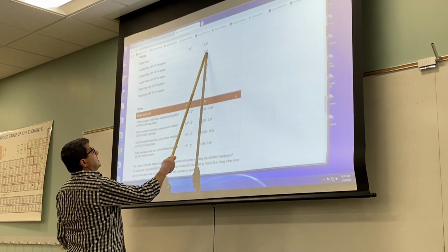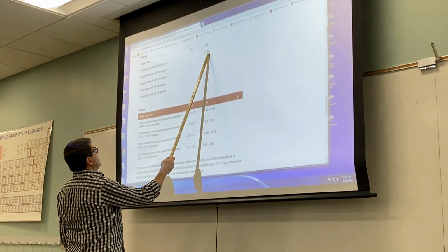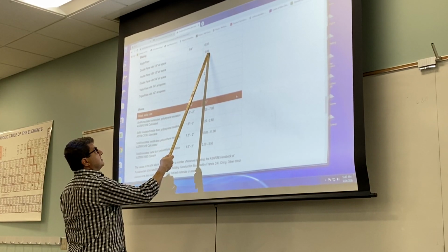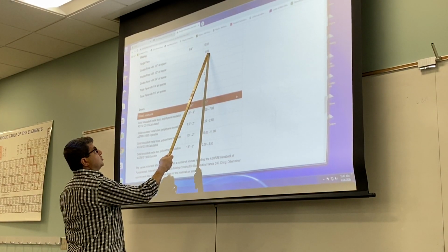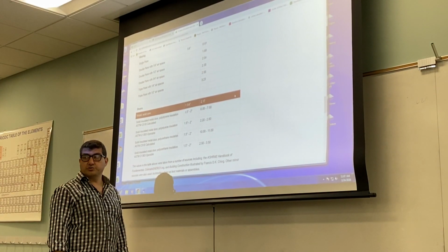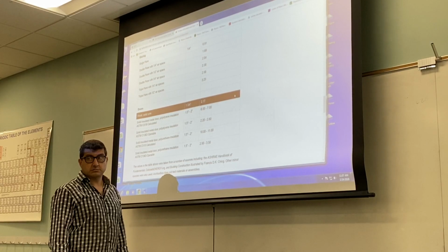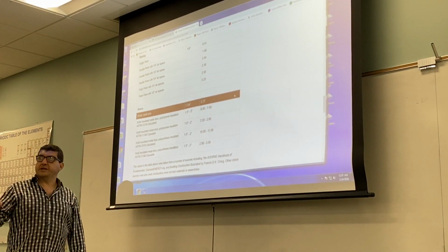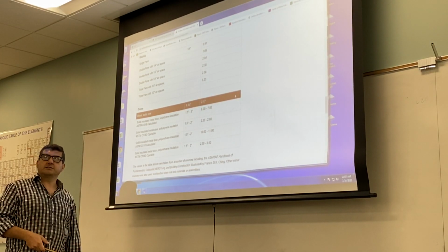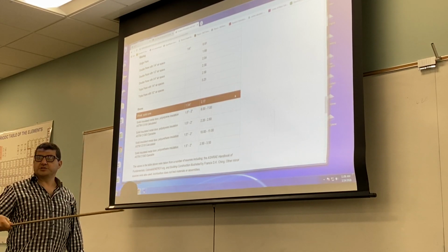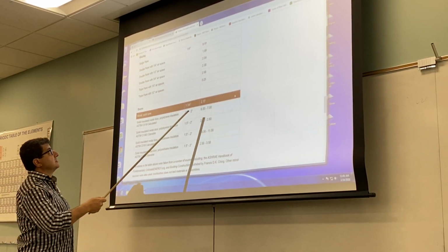You see, by going from a single pane to a double pane with a 1/4 inch airspace, you're increasing the R value by almost 2. So you're decreasing your heat loss through the windows by 2. That's a lot, from single to double. Imagine all the heat you lose through single pane, and then you have to put in heat, electricity, you're spending money, so it's definitely worth it.